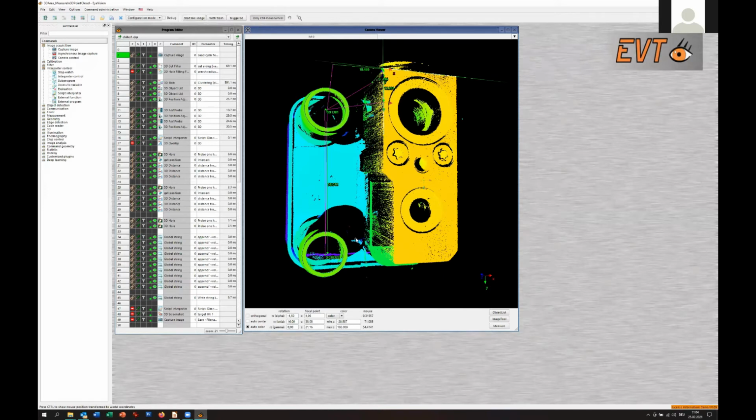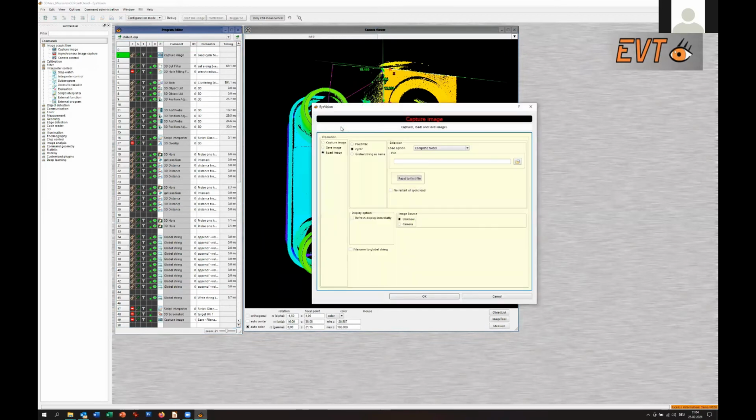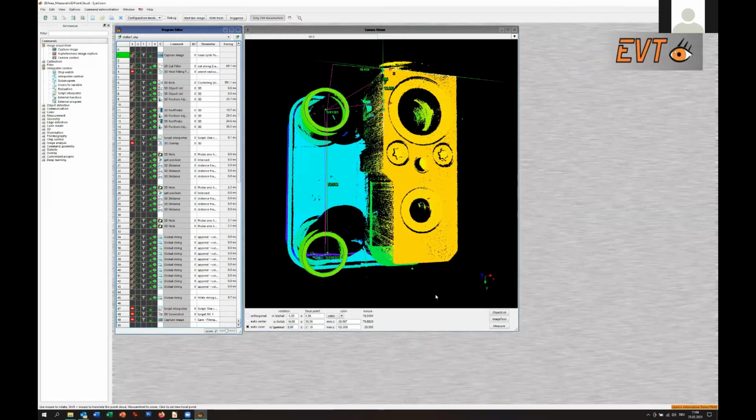And in this case, because the image capture tool is in the option load image, you see we have the option capture image. Now we are in the option load image, cyclic complete folder. That means each time it's executed, it loads the next file from the folder. So you can simulate a complete manufacturing process if you have stored the different point clouds from the machine, and then you can test it totally offline.